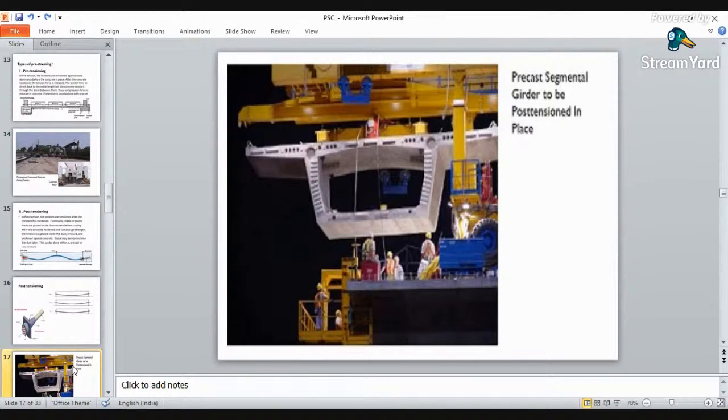And what are various devices used for the post tensioning? Casting bed should be there, duct, anchoring devices, then jack to give the pulling force, then a jack machine, then there should be anchorages, wedges, then strands or tendons, and the grouting equipments. If you have to do the bonded tensioning; if not, then it is an option.